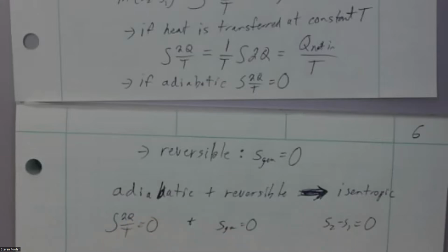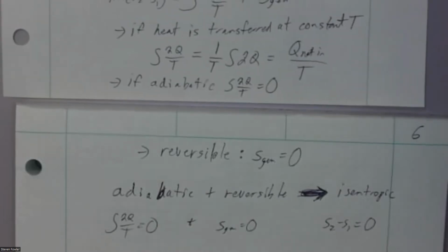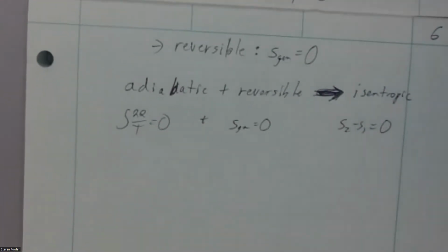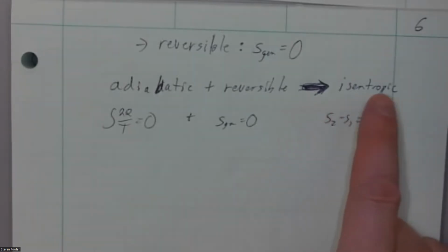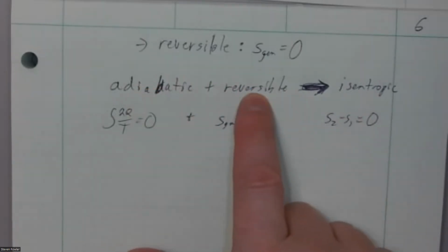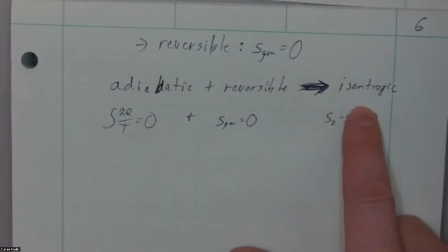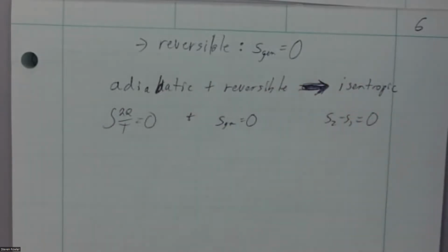So it's not at all an unreasonable thing to have that scenario where this is the negative of that, and therefore it's isentropic. It's not an impractical scenario to say you're never going to encounter it. No, actually, it's not too hard to find examples of that. Hence the arrow. If I know it's isentropic, I don't know it's adiabatic and reversible. If I know it's adiabatic and reversible, I know it's isentropic. Okay, that's critical stuff we got to talk about there.